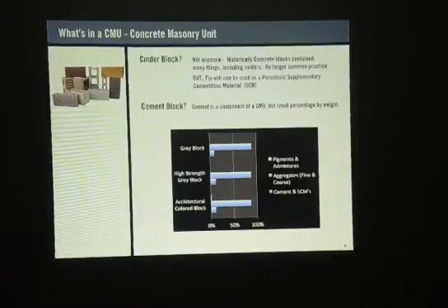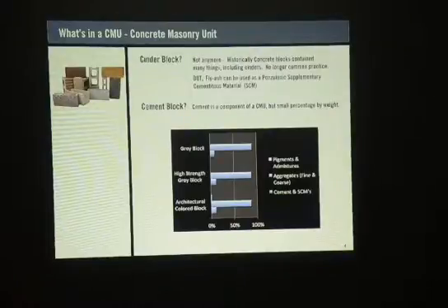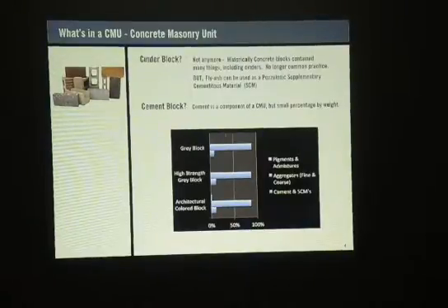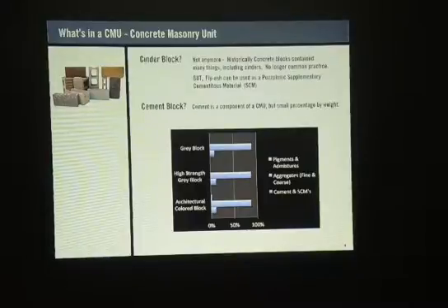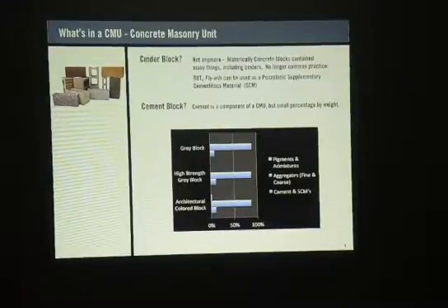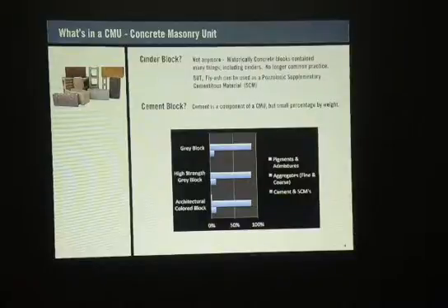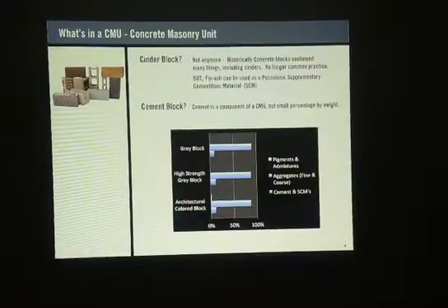But also remember, and we're not going to see anything here, but again, I have to qualify, because they don't mention anything about rebar. Rebar is very important to us, because if properly placed, it can actually be stronger than a framed wall. A framed wall, you know, has minimum load values for shear value and tensile strength, okay? And framed walls have their places. Framed buildings have their places. But a fully grouted block wall with rebar in it has tremendous value.